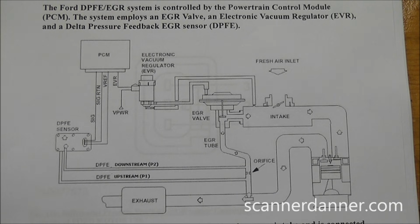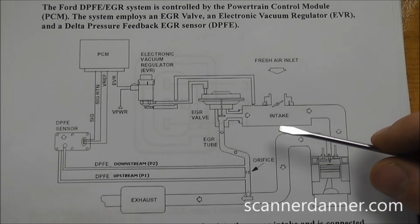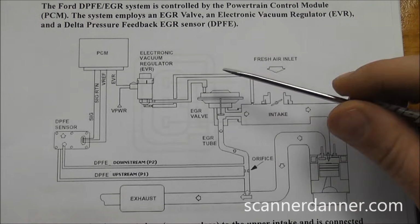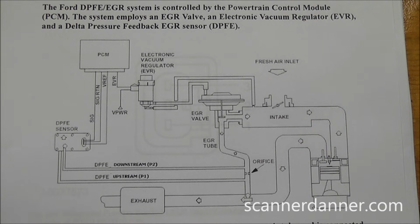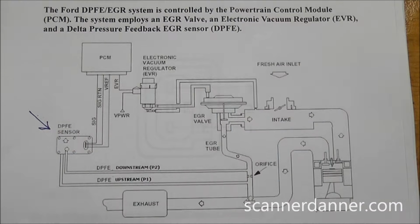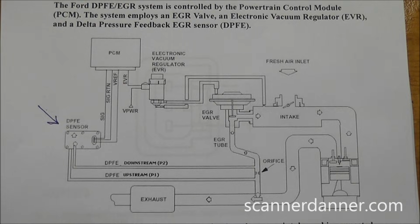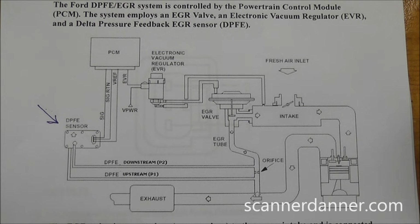Now with this, imagine this, we can kind of get an idea why this is a 34-page flow chart. This system has issues everywhere. I'm just going to mark up this page for a second. We can have an issue as far as an EGR flow code. Now we don't really have a flow code. We have a low voltage code on this sensor. So we're kind of limited with our problem, where we're not going to have to follow all these other procedures, and that's where this 34-page flowchart seems intimidating going into it, but with our particular fault, it really isn't. We can follow the flowchart. We're going to follow it, again, like I said, with my method.